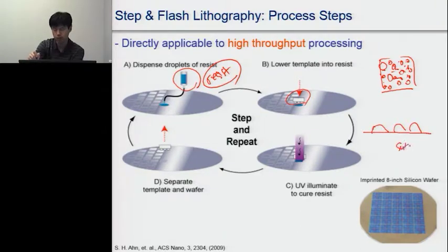This is a substrate, and as the mold goes closer like this, the small resist drops, using capillary force, pull the master mold. At the same time, as these small resist drops pull the master mold, they also connect to each other and form one big drop.